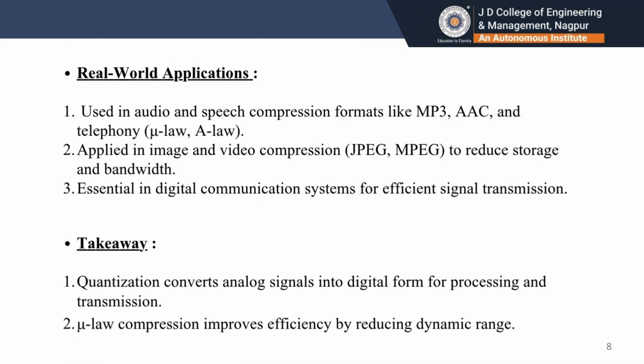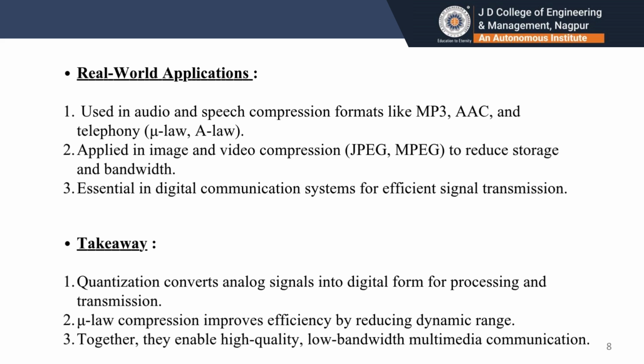The result of this experiment confirms that signal compression reduces the duration of the signal and proportionally increases its frequency. The total energy of the signal remains the same, but it is distributed over a wider frequency range. This principle is very important in DSP applications such as speech and audio processing, data compression, and communication systems where efficient use of bandwidth is essential.